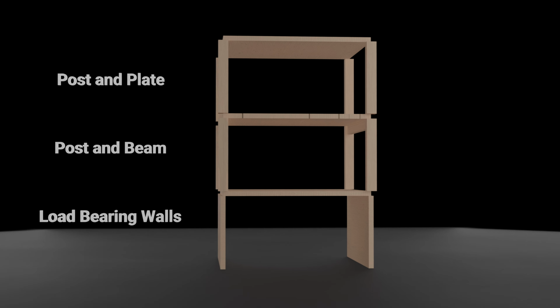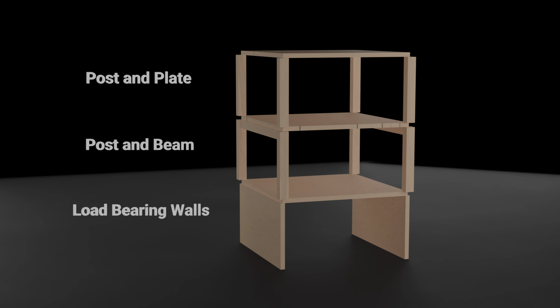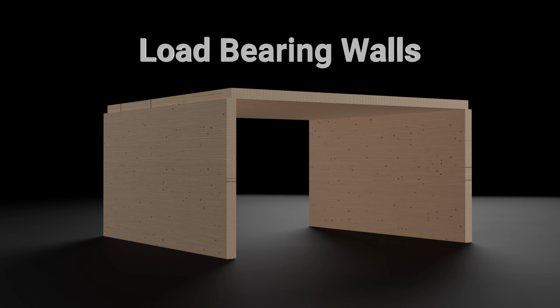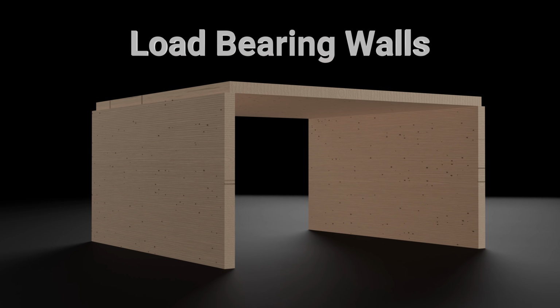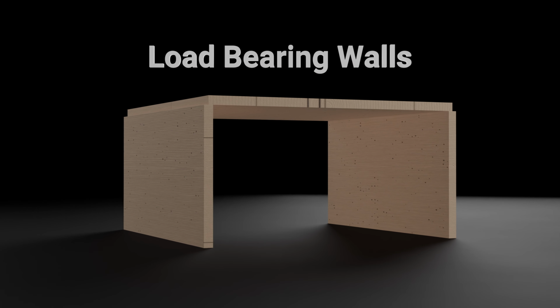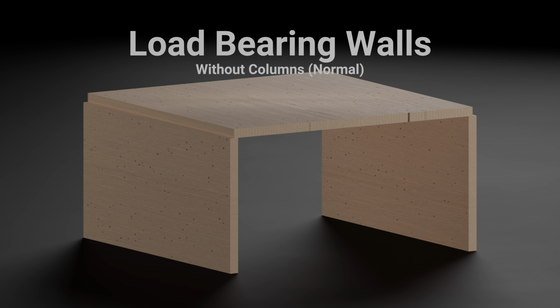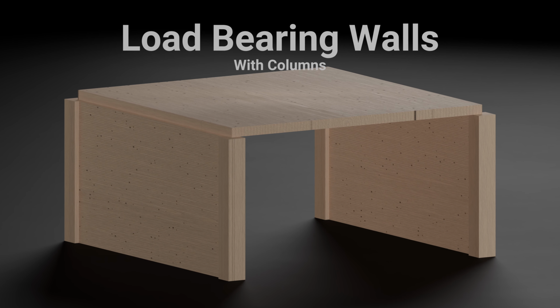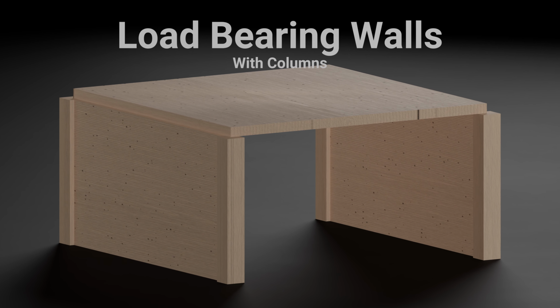There are different types of mass timber framing methods. To start, we have load-bearing walls. In load-bearing wall systems, the walls themselves bear the loads of the upper floors and roof. This system uses thick walls that often serve both structural and insulating functions. It can be used as a standalone system or in conjunction with columns for added support.